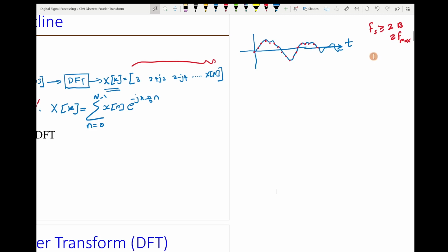If I take this to be 1 second, and this we usually call the interval or the window, then there will be a delay. As I'm speaking for 1 second, he is waiting, then he starts hearing, while I'm already talking and he's responding to my information from 1 second earlier. So to avoid this lagging in audio processing, usually they make this T0 equal to 50 milliseconds.